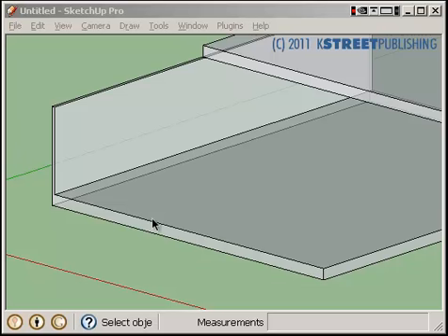Here we have two floors. These floors are both framed out of TJIs, which are 11 7/8, plus plywood, 3/4 inch. We need to build a stair between the two. Well, when you're working with stairs, one of the main constraints is the code allowances. The building code allows you to have stairs of only a certain height and a certain tread width.